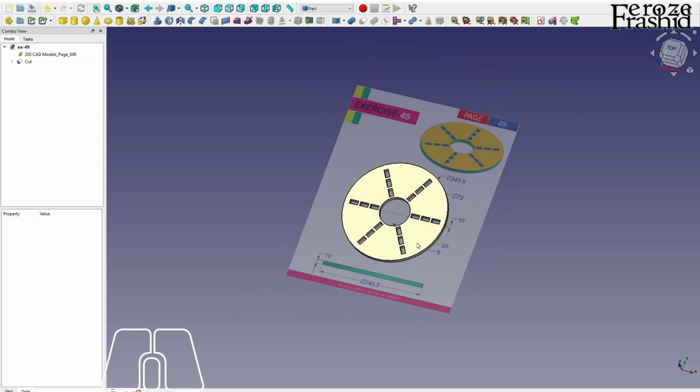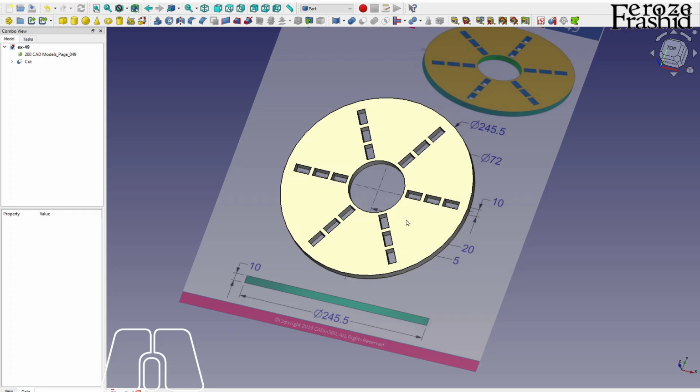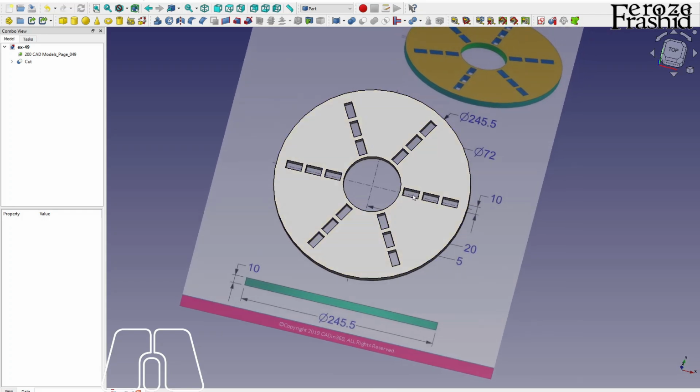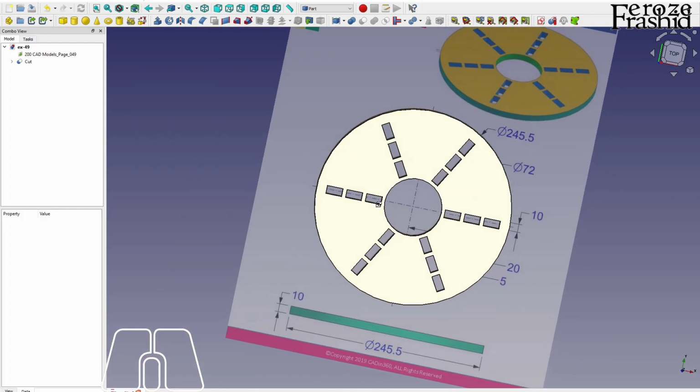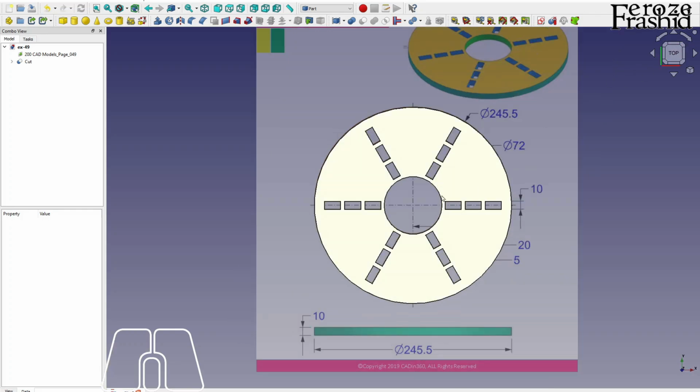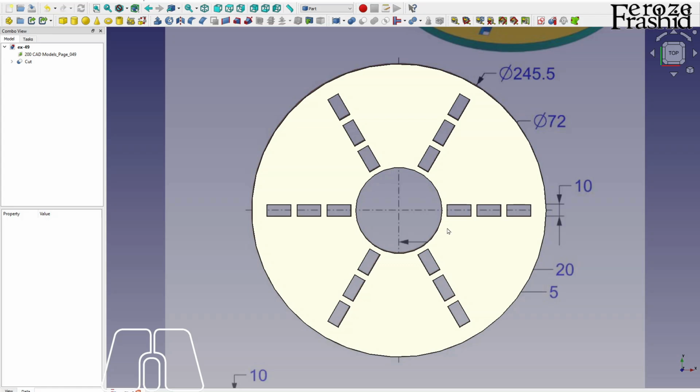So in exercise 28, the previous one, I took a different approach where I did polar array 3 times to create these 3 replicated units in a circular fashion. This one, as you saw me using a different approach, where I did the linear array first and then polar array. Between these two, I would definitely go with the one that I just used in this model.